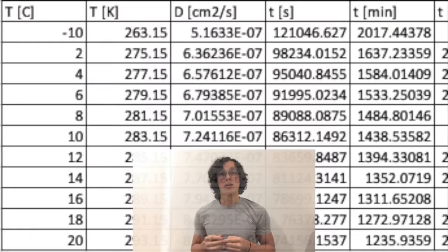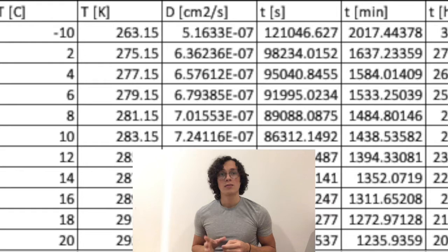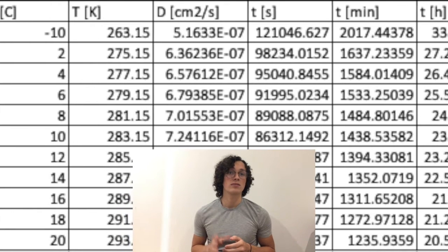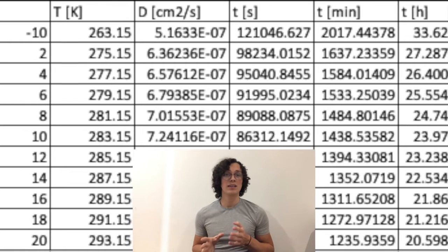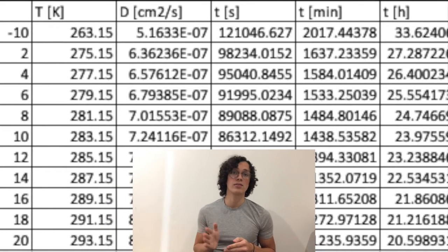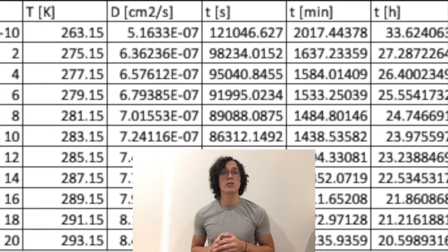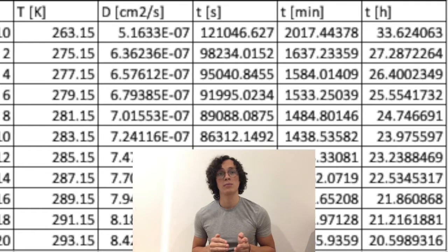And so it was obtained that around 22 hours were needed for an 80% saturation of a single zeolite bead, which is a result that indicates that we must change the functioning molecular sieve bed in around 22 hours to diverge the flow to the second molecular sieve bed.